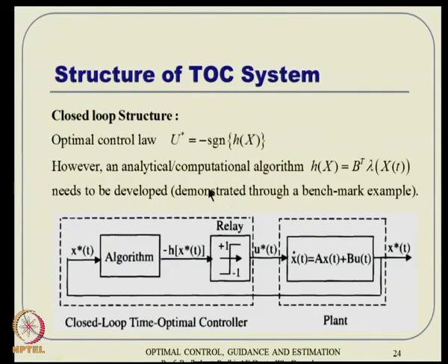Alright. So, again, as I told, that is not very elegant. What you are looking for is something like a closed loop structure. In other words, control should be some form of a state feedback. And remember that in a regular LQR system, where the objective was also fairly similar, but we did not have this control constraint in place, we had u transpose equal to minus R inverse V transpose P times x. So, essentially we have a closed form formula in state feedback form. So, here also we are looking for something like that. Is it feasible or not?